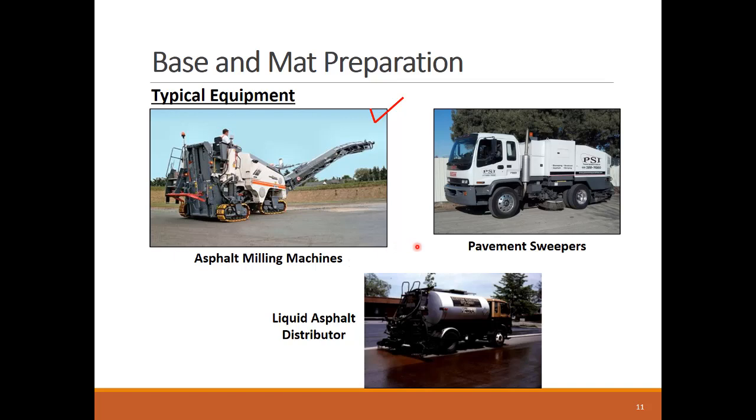Sweeping trucks are used after milling machines to clear the surface from dust and foreign material that can reduce the cohesion of the surface with the new pavement. After sweeping, the liquid asphalt is sprayed using the distributor trucks.